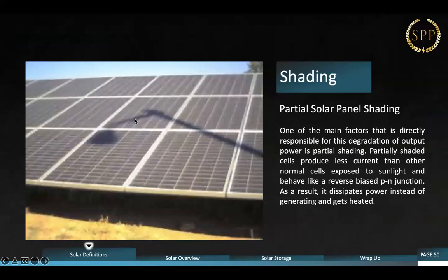Okay. Now what's happening? Has the voltage changed? No. So the pressure hasn't changed. But what ends up happening to the actual current? Well, it's just like kinking that hose up. You have the pressure still pounding away at that cell, but it's not producing what it should. And eventually it's going to start heating up the actual panel itself. It could cause problems for that panel and help degrade it even faster than it should have.